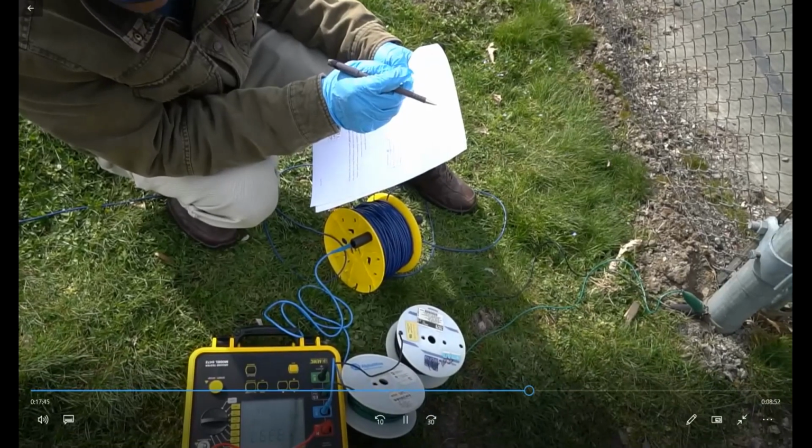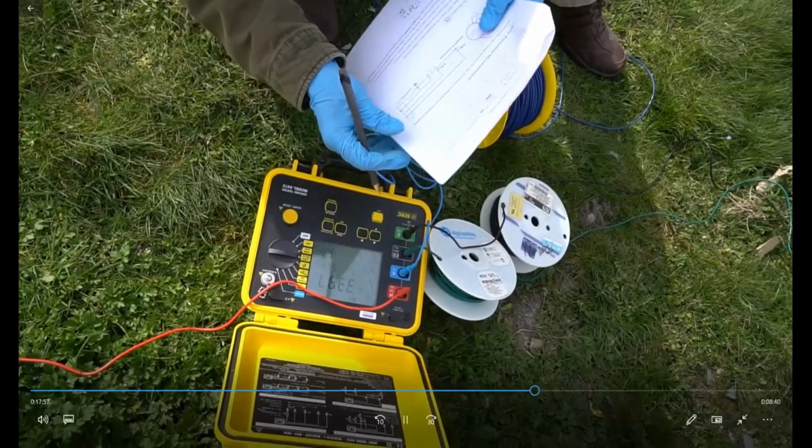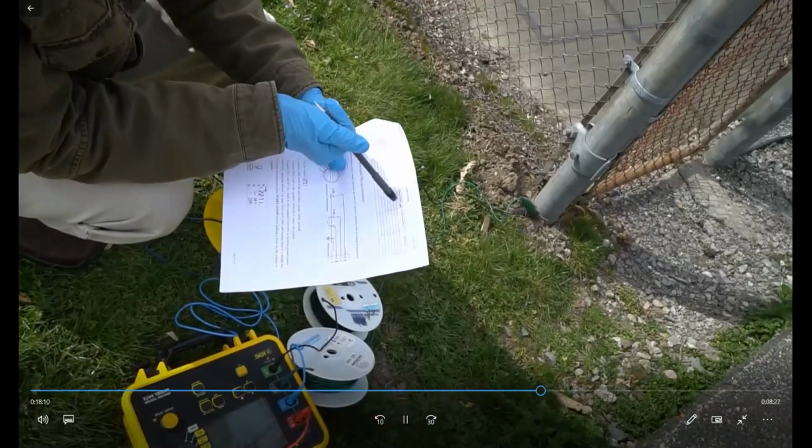this resistance times the short circuit current. But in reality, short circuit current is not that much and voltage is not that much, different things. So here we have to put the amount of current that represents the real short circuit current, and with that current we have to multiply this value, that will be our touch potential. Okay, this is just the resistance.